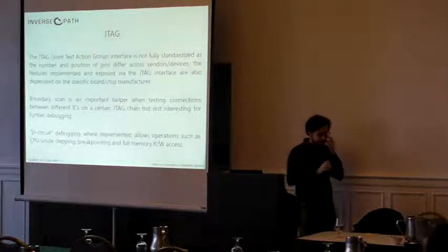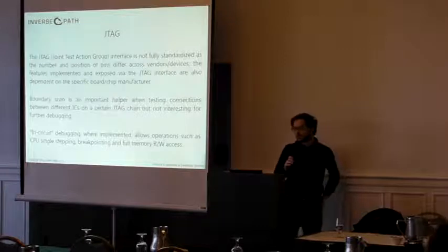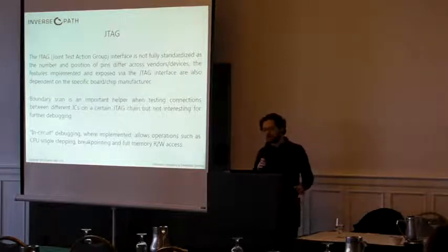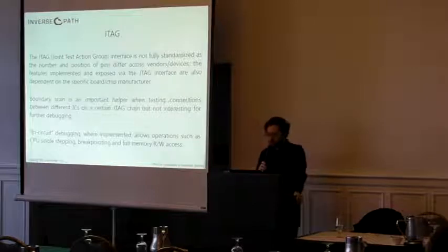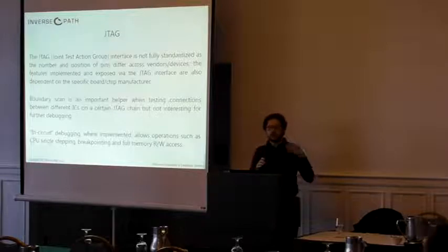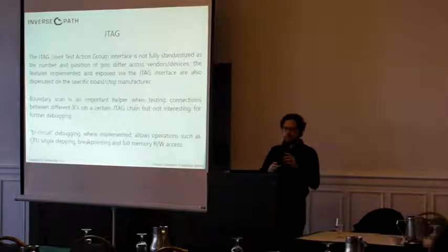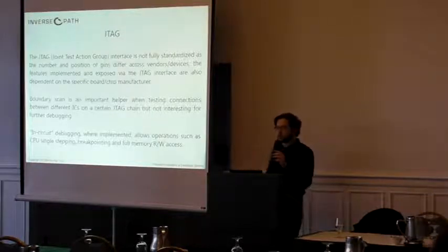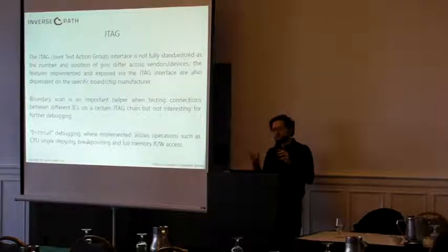JTAG, on the other hand, is a bit more complicated because, despite being a standard, the standard doesn't tell us too much about how things should be implemented. And JTAG is really powerful. It allows you to do in-circuit debugging, and you can step the CPU, you can do breakpoints, you can have full memory read-write access, and sometimes it's really critical to get JTAG access in case, for instance, you have a